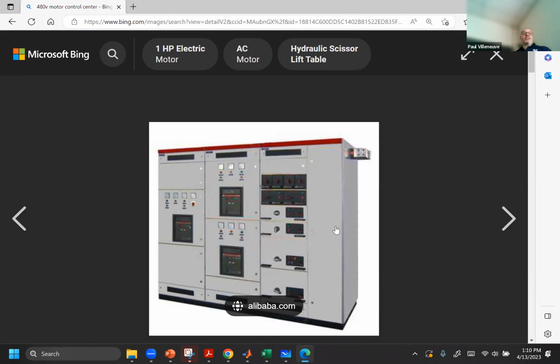And good electrical practice is we have some control wires that maybe we want to stop something remotely. And remember that stop, we saw that CPT was only 120 volt AC. We would isolate 120 volt from 480 volt. So we would run those in different raceway to make sure that people don't mingle too much with that stuff. And then you can have wiring coming in overhead or below ground. Which do you think is best?